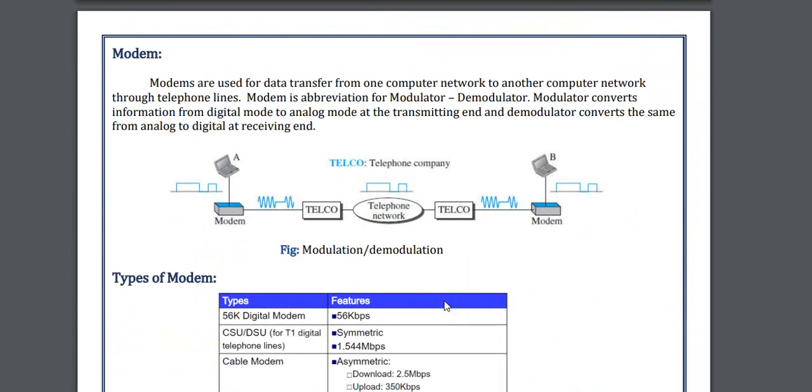The last section of this lecture is the modem. The modem stands for modulation and demodulation. On the sender side, the data is sent as a digital signal, and then the modem works on it and generates an analog signal. The DA converter, which converts the signal from digital to analog, is the work of the modem. When it is closer to the receiving side, the demodulation generates the digital signal from this analog signal, which is the AD converter, and is the work of demodulation.